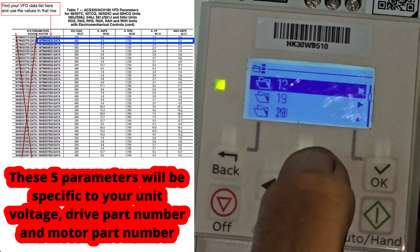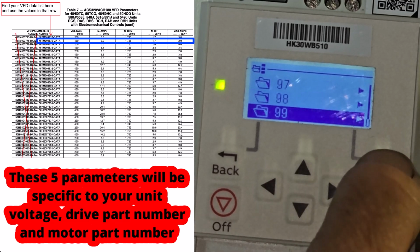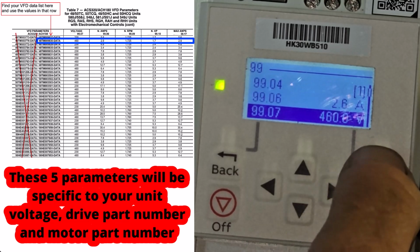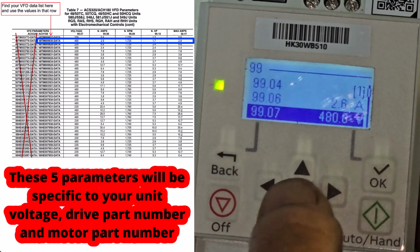Enter parameter group 99. Scroll down to 9907 and enter your unit voltage, or enter the voltage measured on site. For this example, this will be 480 volts.